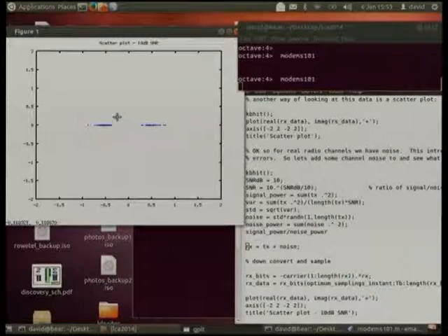So as the signal to noise ratio drops, the spread in the scatter gets bigger, and eventually you start generating bit errors. A good modem will have fewer bit errors for a given signal to noise ratio than a bad modem. So that's the scatter diagram showing us the effect of adding noise to the radio channel. At 10 dB you can still see there's no bit errors there. None of those have even got close to the middle line, which is pretty good for digital communications.